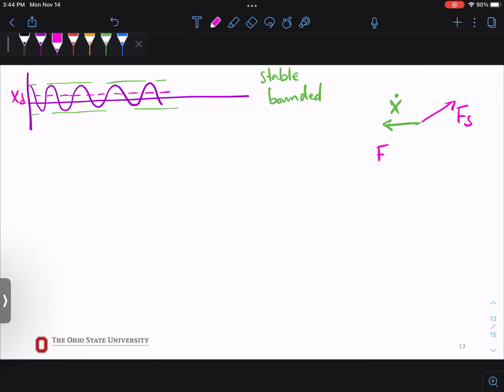So this Fs transpose times our x dot will be less than 0 for all the x dot that are not 0, when the system is moving. Then we can say that our Fs is some kV value times x dot. If we change this kV, if we manipulate it, we can decide about the value of this Fs that controls the velocity of our system.